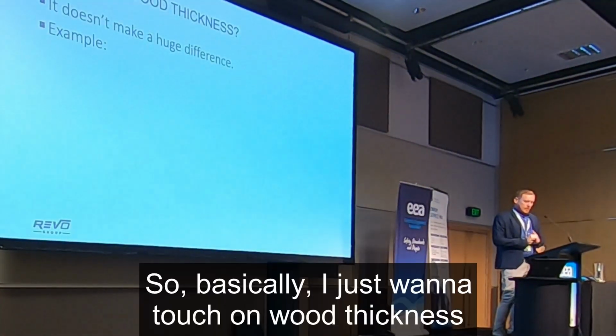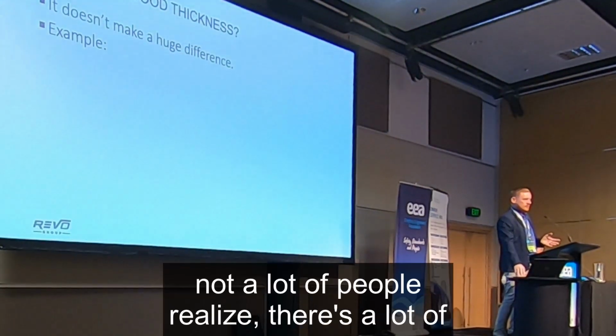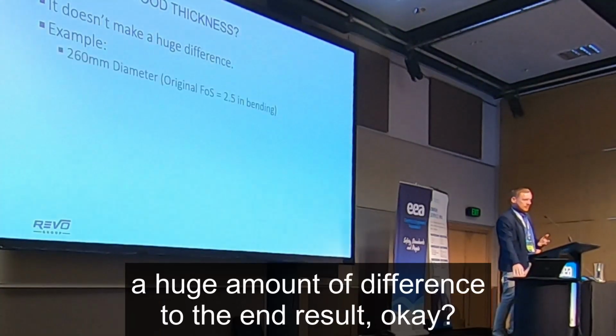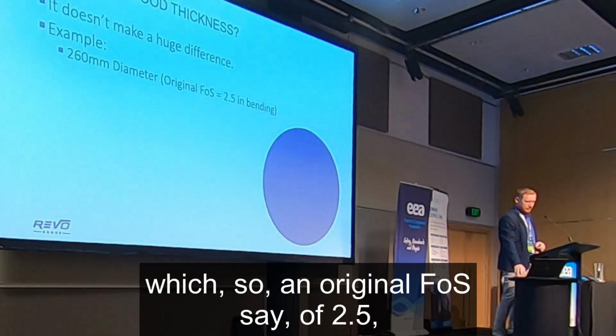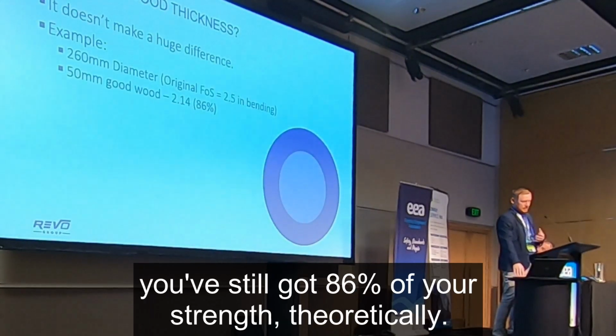So basically, I just want to touch on good wood thickness for a little bit, because not a lot of people realise there's a lot of emphasis on it. It actually doesn't make a huge amount of difference to the end result. Okay? So if you've got a 260mm diameter pole, which say has an original factor of safety of 2.5, and you've got 50mm of good wood remaining, you've still got 86% of your strength, theoretically.